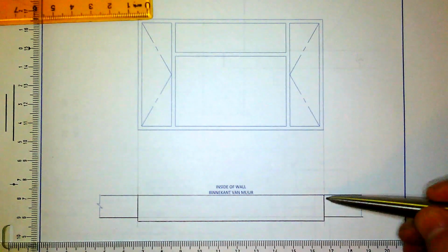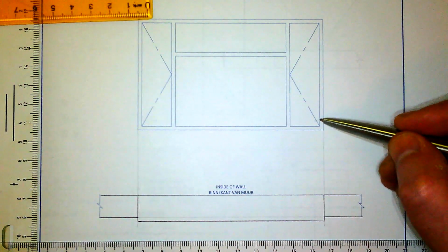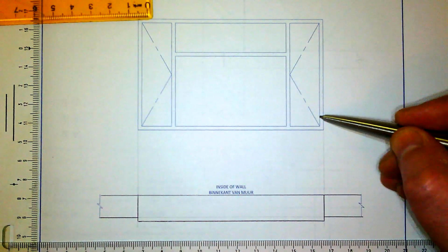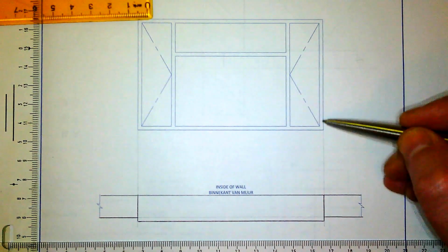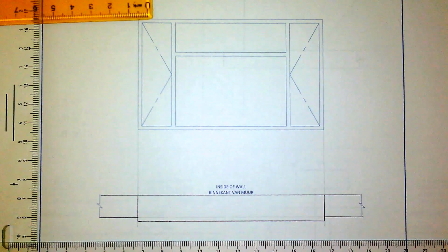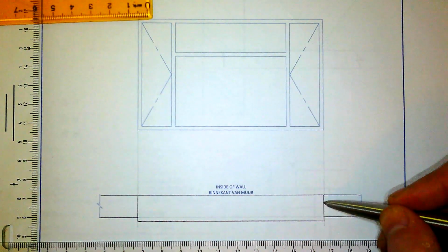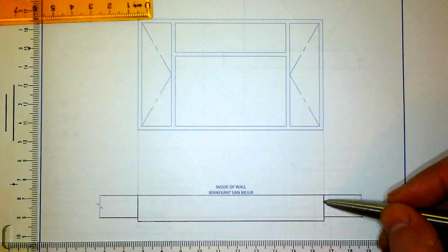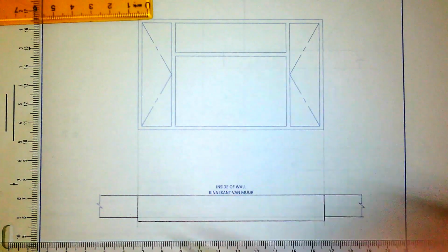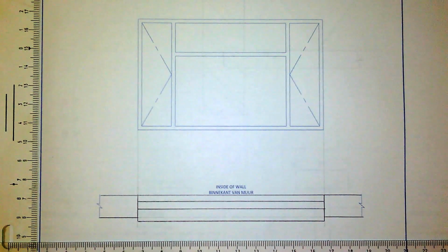Okay, now we don't actually know how thick the frame of the window is because we can't really assume that it is as wide as it is long here. So we can't see the side thickness, so I'm just going to make up a thickness there, and it's normally not square anyway, so I'm going to take roughly 1/3. So whenever you do the symbol, if you're not sure what the thickness of the window will be, just take about 1/3 of the wall and you take that across. That's it, guys. How easy is that, eh? So you just have the sill going over a little bit.